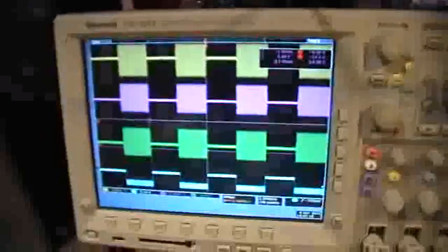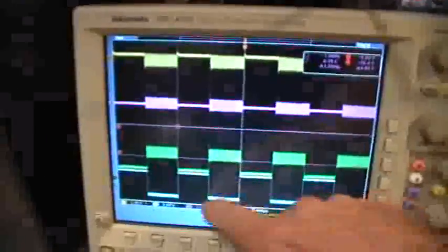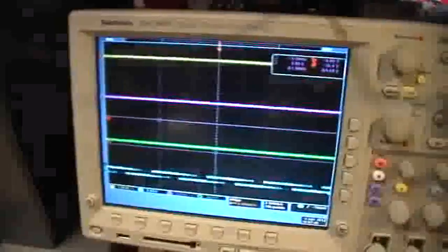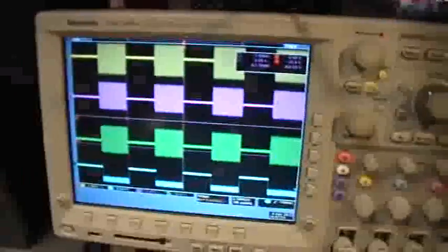But watch what happens if I push the drive pulse up to positive and turn up the amplitude. Okay. Now you see what's happened? The voltage on the current viewing resistor has gone up. So that indicates there's current flowing. There's oscillations, battery trace. So in this way, with the current up above the baseline, we know there's current flowing through the CVR. But we know that we're supposed to be using a negative offset, right? And that's where that is, just like that.